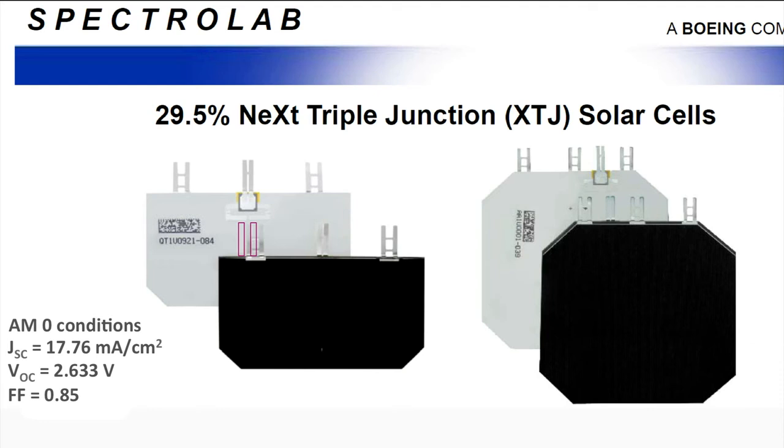This means that up to a band gap of 0.67 electron volts, we have a spectral utilization expressed in current density of 53.4 milliamps per square centimeter. Theoretically, this spectral part can generate 62 milliamps per square centimeter of current with an EQE of 100%. This means that this triple junction of Spectrolab has an impressive average EQE of 86%.